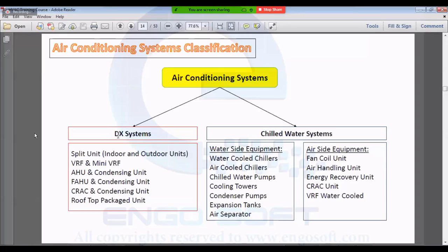By mixing the outdoor air with the return air, the resultant air has a mixed temperature, which is the temperature of the mixing air. So the cooling load will be 100 liters per second, multiplied by the heat capacity, multiplied by the mixed temperature minus 24, which is lower than in the case of the fresh air, right?